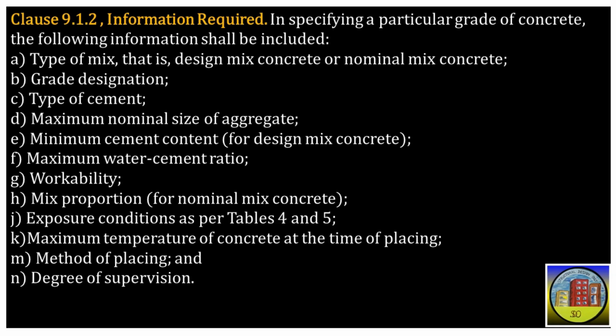A. Type of mix, that is, design mix concrete or nominal mix concrete. B. Grade designation. C. Type of cement. D. Maximum nominal size of aggregate. E. Minimum cement content, for design mix concrete. F. Maximum water cement ratio. G. Workability. H. Mix proportion, for nominal mix concrete.